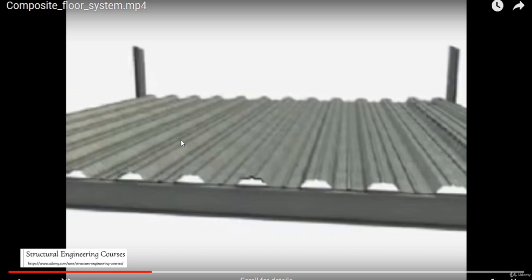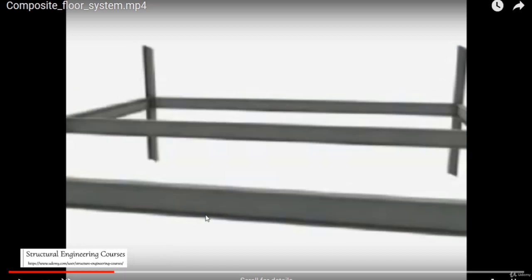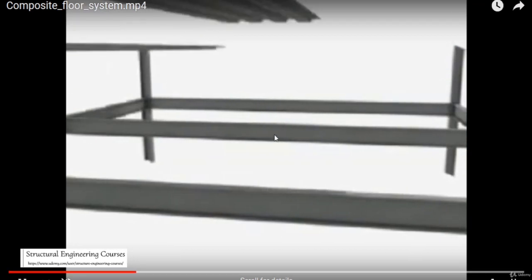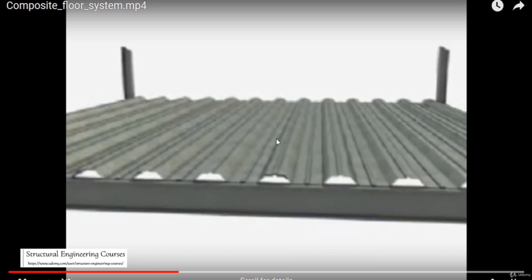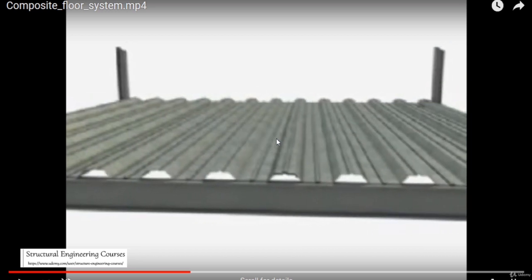They simply don't understand what should be the orientation of these deck sheets. So this is the golden rule, that these grooves shall always be parallel to the shorter span, not parallel to the longer span. Because otherwise, as I also explained to you the system of the one-way slab and two-way slab in the previous lecture. So the deck sheets are almost all of the time laid on this one-way system only.